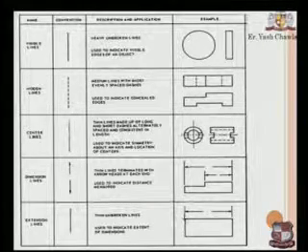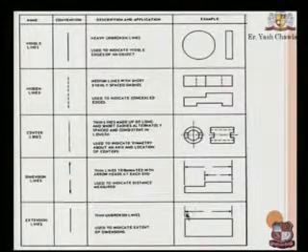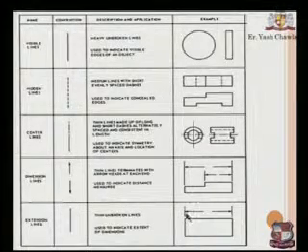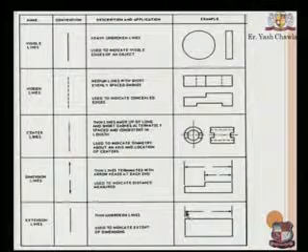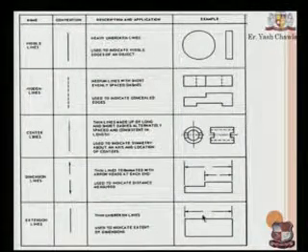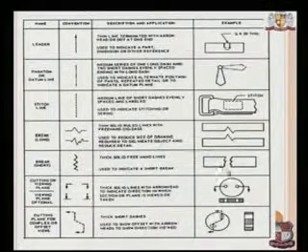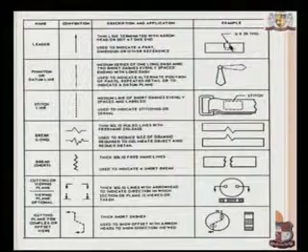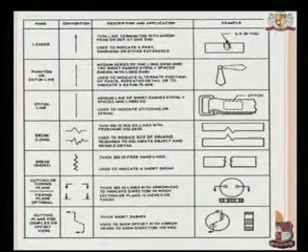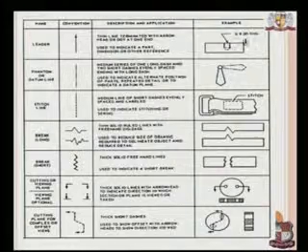Extension lines, these are particularly to show the dimensions. These lines have an endpoint, so we take this as the endpoint, and we consider these rays end till here, and we can give the dimension again here. The leader line, this shows where we cannot directly write, or say the distance between the two endpoints is very small, we use the leader line to show its diameter or its measurement or whatever.